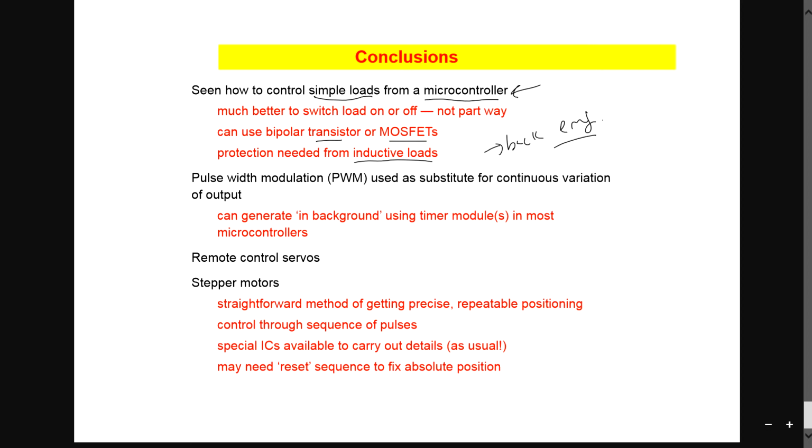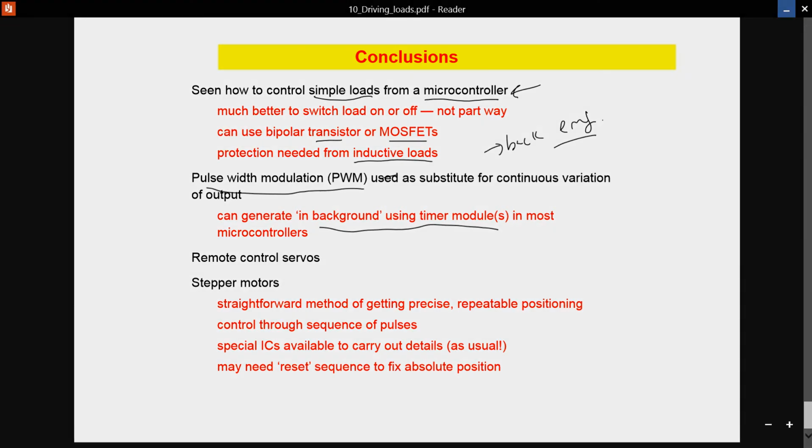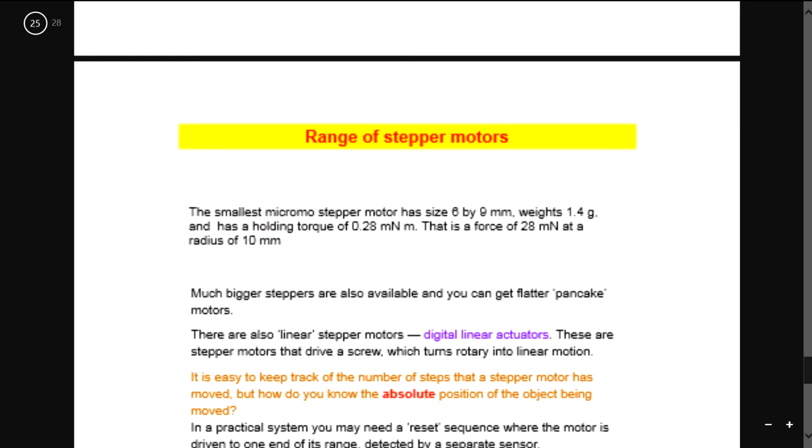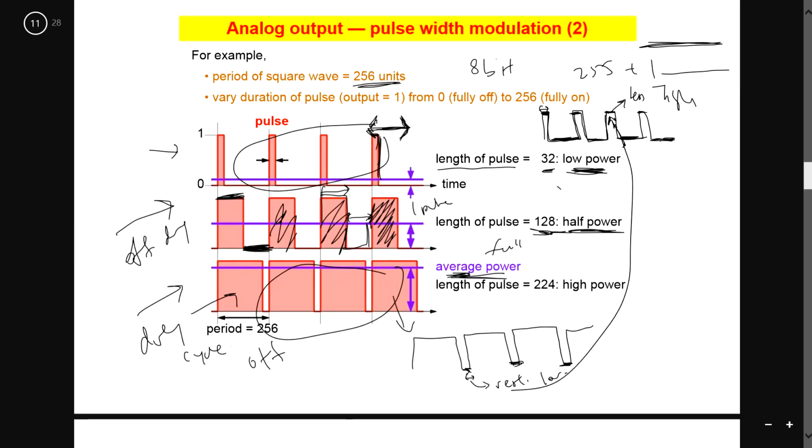And nonetheless, you need to take note when you design your motor. You can drive your motor with pulse width modulation, something like turning your LED light on and off. You can run it using your software to control the timing of the pulse width. These pulse widths, as I showed you, generate different variations of your power. Normally when you use the bipolar, it can only be full power or no power. If you want something in between, you can use the pulse width method.